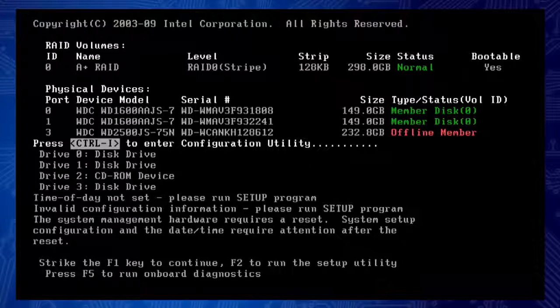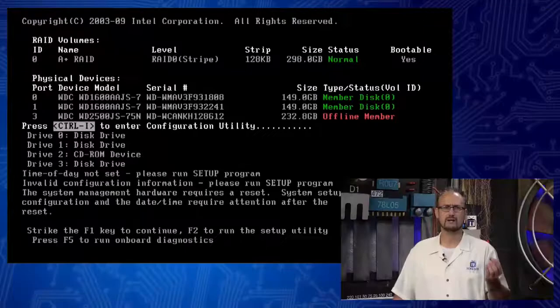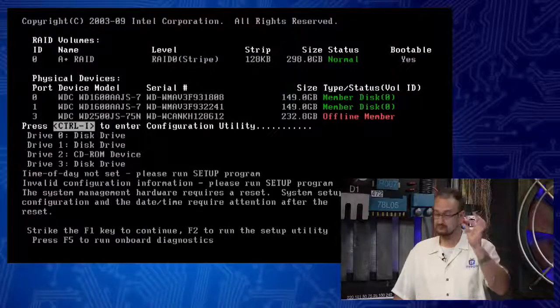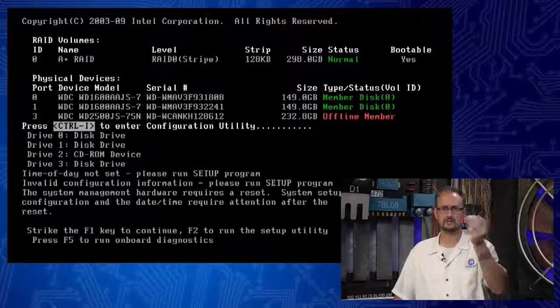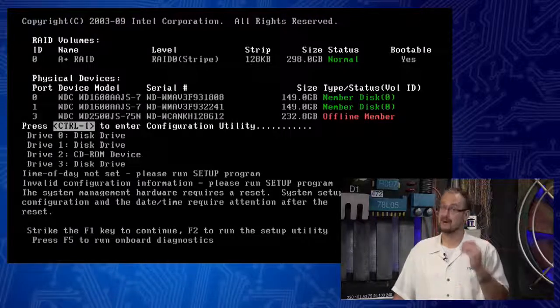All right, well, what's going on is this little battery that we have inside of the motherboard has failed to do its job, right? And this is indicative of some kind of CMOS battery failure. Now, what battery do I mean? Well, I've actually got one right here in my hands. This is it. It's a little, I believe, CR2032 3-volt watch battery. There's nothing really special about it, except for in your computer. There's something very special about it.